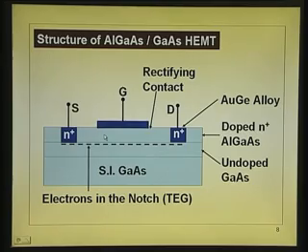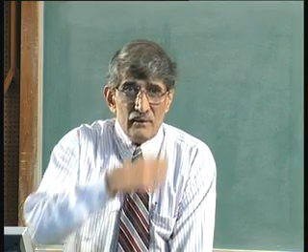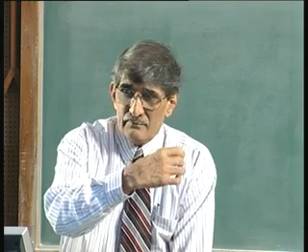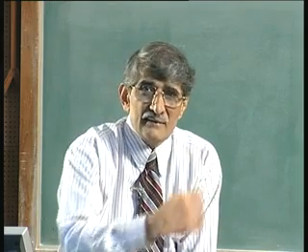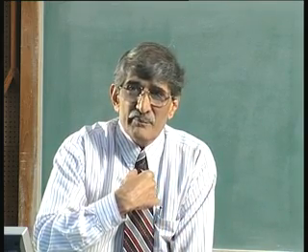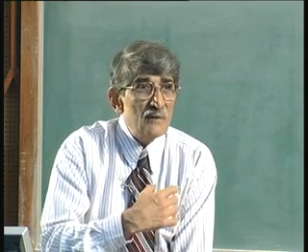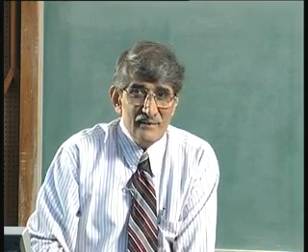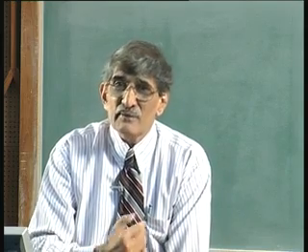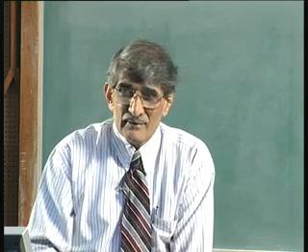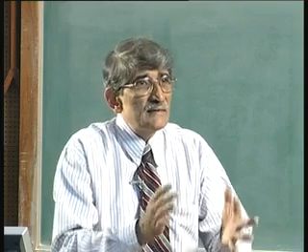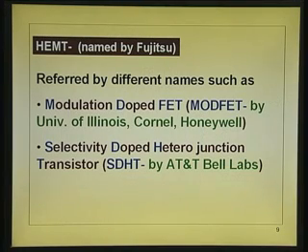In the previous lecture, we discussed gallium aluminum arsenide, gallium arsenide, etc. One diagram we put where none of them are doped. Another diagram we put all of them are uniformly doped. Another diagram we put where only GaAs is doped, that is modulation doped. To tell you that only the selected regions are doped, you also call it selectively doped field effect transistor. So, here the modulation doped means actually it is doped in selected regions.